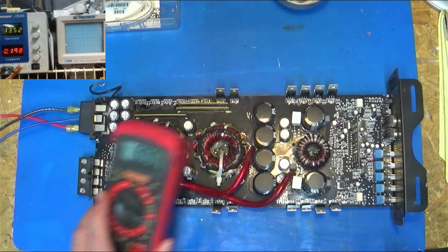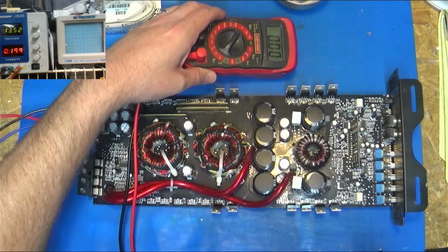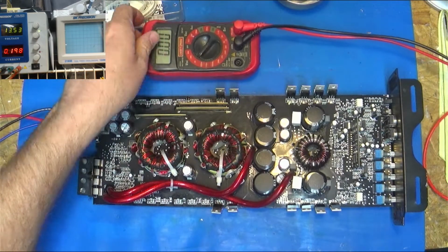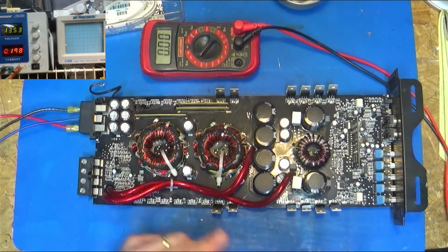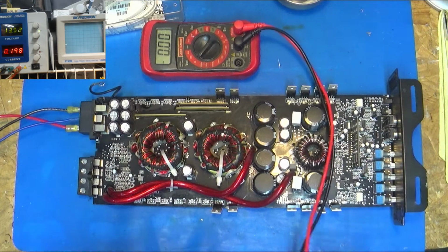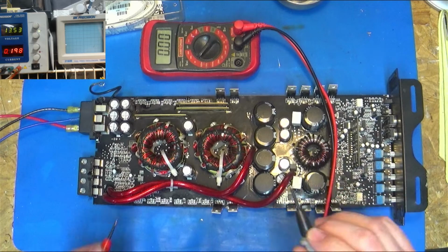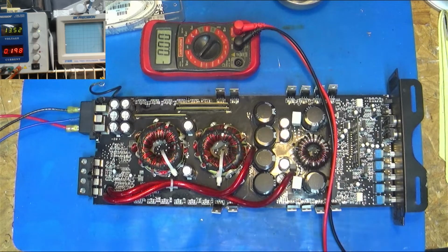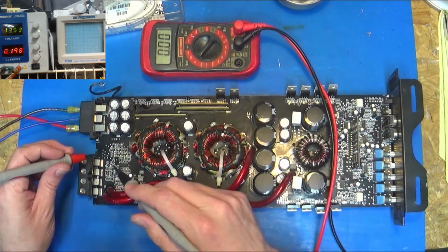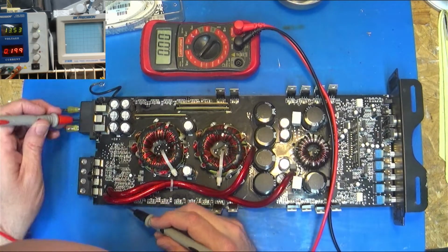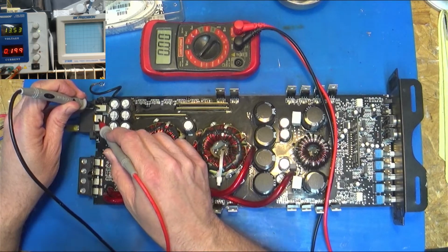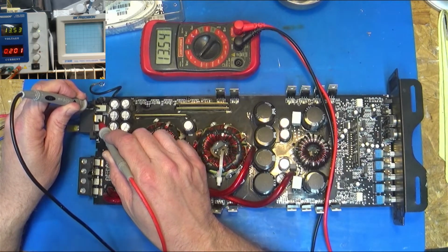So if we take our multimeter on voltage here, let's turn this where I can get to it. You can see up in the corner I have my power supply on, and we're going to turn on the remote. Those numbers happen to be exactly right in that schematic. They actually happen to be the correct stuff. So we can place our probe on ground, and we can measure and see if we're getting voltage here. Yep, we are.